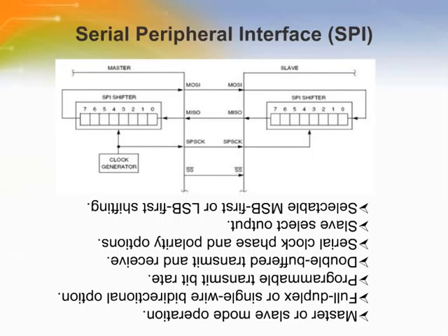The Serial Peripheral Interface (SPI) module provides for full duplex synchronous serial communication between the MCU and peripheral devices. These peripheral devices can include other microcontrollers, analog to digital converters, shift registers, sensors, memories, etc. The SPI runs at a baud rate up to the bus clock divided by 2 in master mode and up to the bus clock divided by 4 in slave mode. Software can poll the status flags, or SPI operation can be interrupt driven.